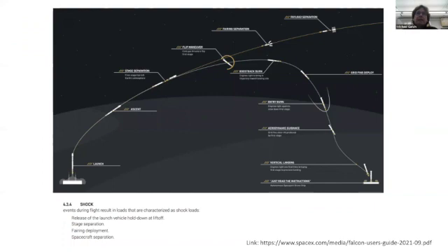So the next environment that you might be interested in measuring with an accelerometer is a shock environment. And a shock environment is basically just a very fast transient vibration environment that decays very quickly. So it's not a sustained vibration. It's a short transient vibration, but it can be very strong. It can be a very violent vibration for a very short amount of time.